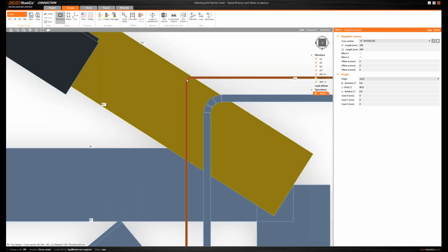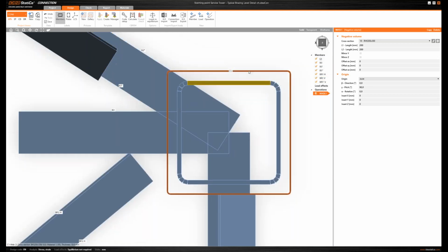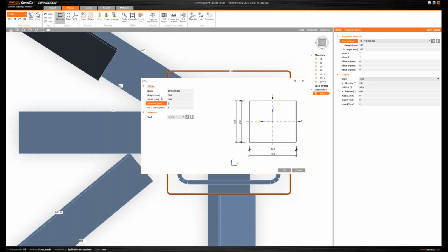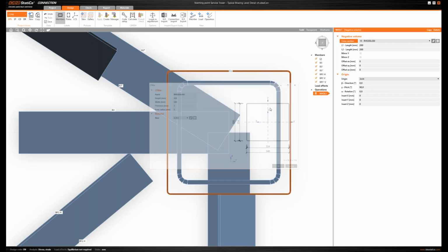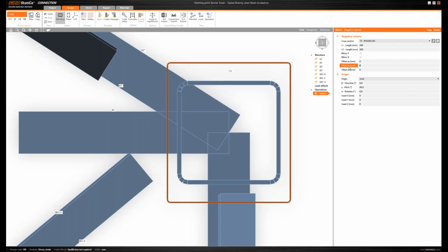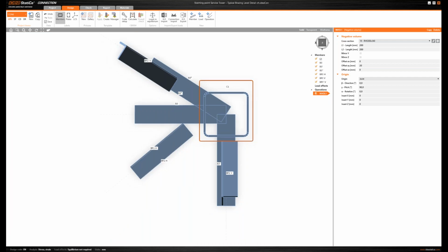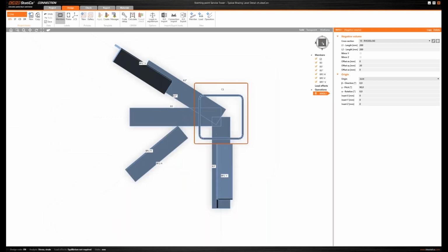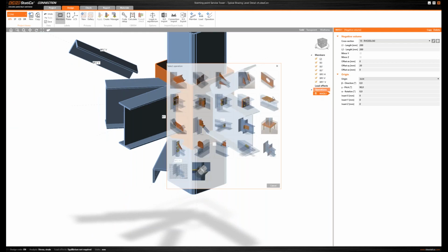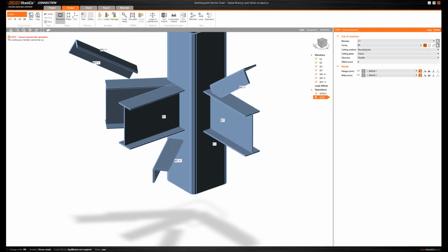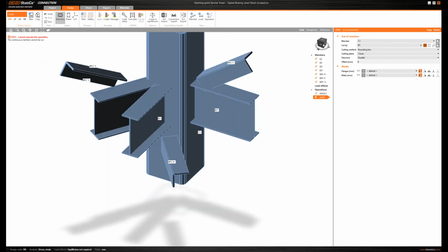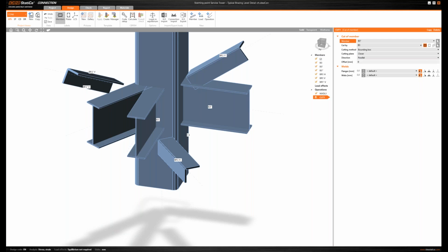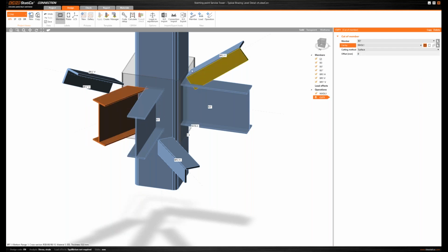Please notice that here we have the beam that falls straight on the rounding of this cross section. So I will move back to the definition and slightly increase its dimensions. And at the same time, I will add an offset, which will maintain a constant distance from all beams. And next, I will use the cut operations and start cutting the beams one by one. So I will start first with this beam, which is B3 quote, and I will cut it using the negative volume.